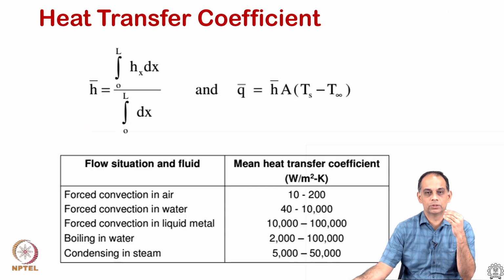So, heat transfer coefficient, as we discussed in the last introductory material, there are forced convection, natural convection. Typical mean heat transfer coefficients are on the order of 1 to 10 watts per meter square Kelvin,